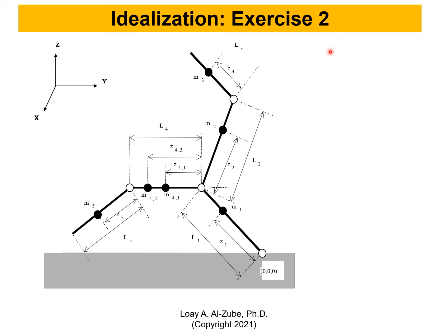Step 1 is idealization. And this is supposed to be a deer. And here's the thing. Rule number 1, you need to have a starting point. You need to have a 0, 0 point. Make sense? That's rule number 1. Rule number 2, which is important: we cannot have closed loops. So when you build your model, we can't have this connected to this point, these 2 points. Does that make sense? If we do this, the model will fail. We're not going to work with our model.